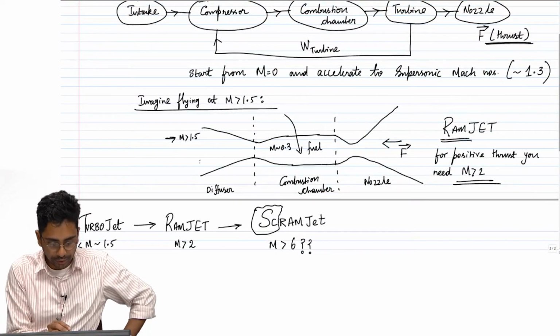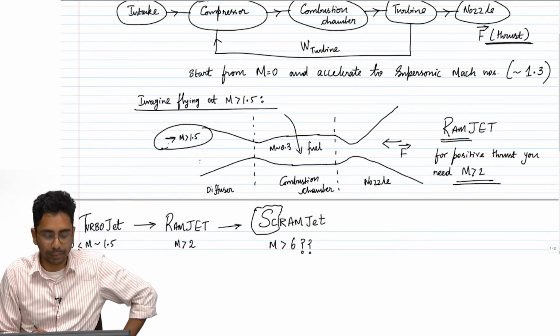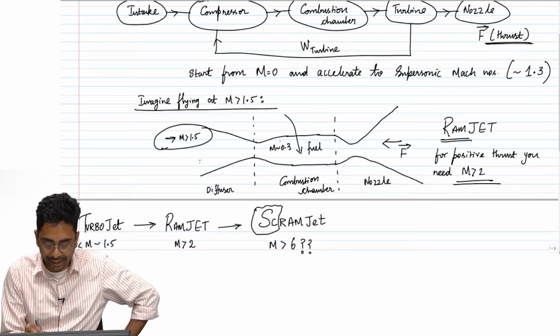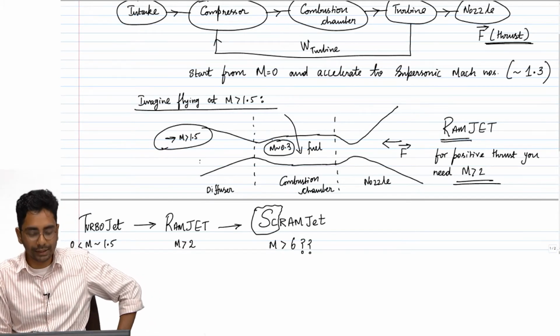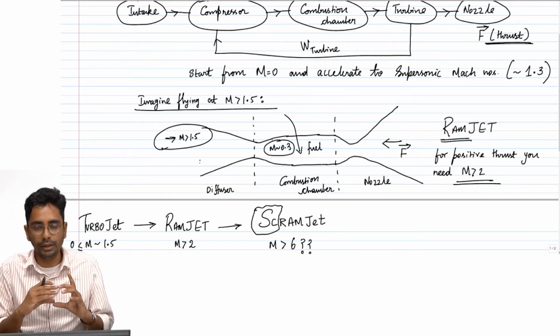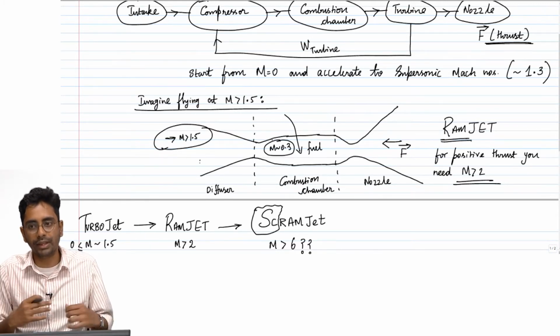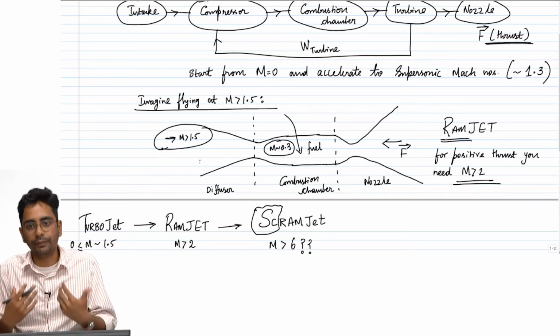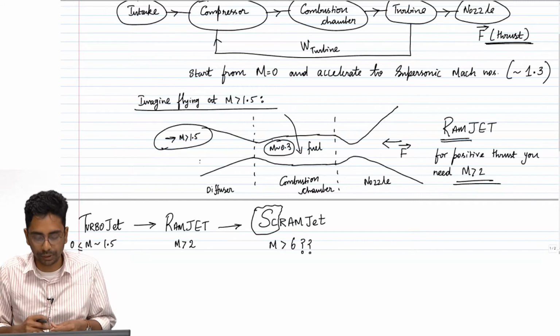In a ramjet you had a stream coming in at Mach 1.5, which was decelerated to Mach 0.3. And this deceleration has to be done in a short distance. You cannot afford to have a long, nice diffuser arrangement, because the longer the device, the higher the weight, and therefore you need larger forces to keep that object afloat.